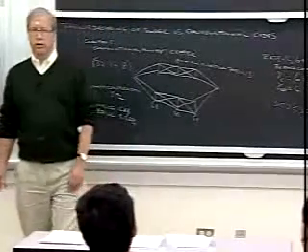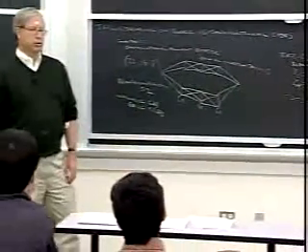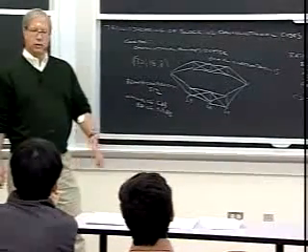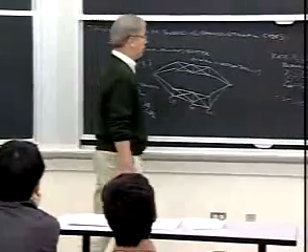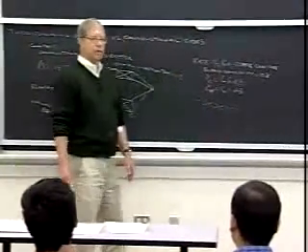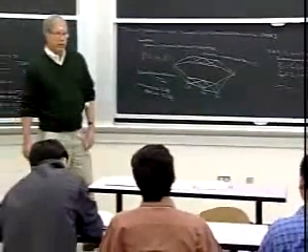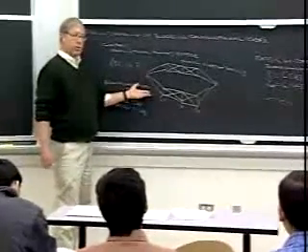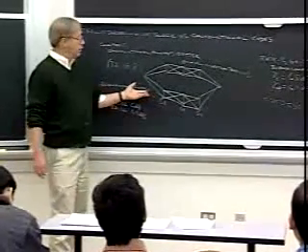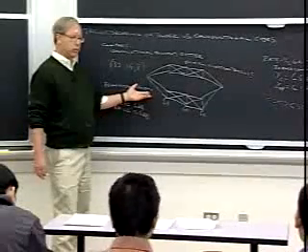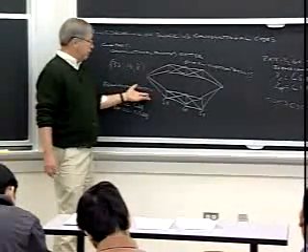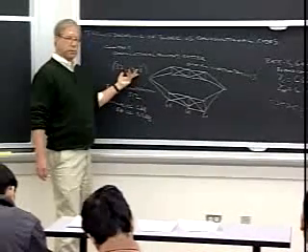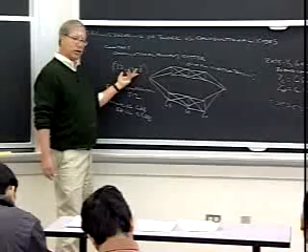But whichever way you do it, making it a block code, you lose something. With termination, you don't lose minimum distance, but you do lose rate. You have to put in some dummy information symbols, so the rate becomes less than 1/2 if you terminate this code. Nonetheless, as I believe I commented earlier, that's a good way to come up with good block codes, is to terminate a good convolutional code. If you choose the parameters right, you can come up with pretty good codes. But nonetheless, in terms of block code parameters, you're not going to do better than what 50 years of algebraic block coding theory has come up with.